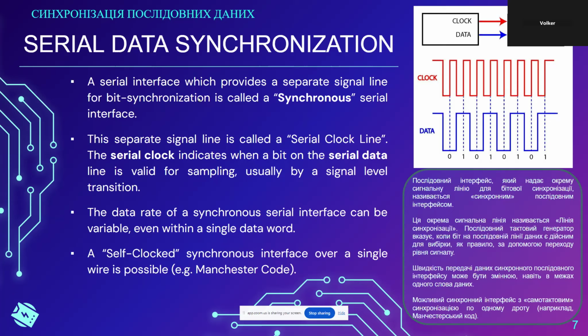So it is possible that the clock can vary, or can even stop for a short period of time, for example when the serial interface is implemented by hand, not through an actual peripheral device in the microcontroller. We're going to talk about that as well, what it means to bit bang a serial interface. That's the colloquial term for doing this.